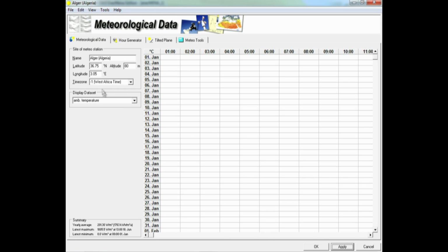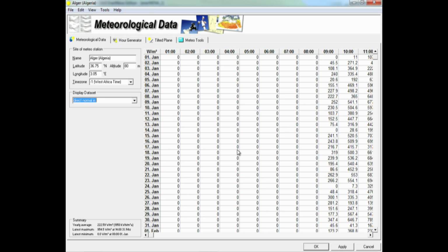If we switch back to the data table, a situation may occur that you have measured irradiance data for a specific site, and for any reason, some of the data are missing for certain hours. Greenius needs a full data set, that means 8,760 hours per year, and if some hours are missing, you run into trouble for the simulation. In order to modify your data set, you have several options. You can either just copy the hour before or the hour after the certain hour where the data is missing, or you use a kind of interpolation for that missing hour.